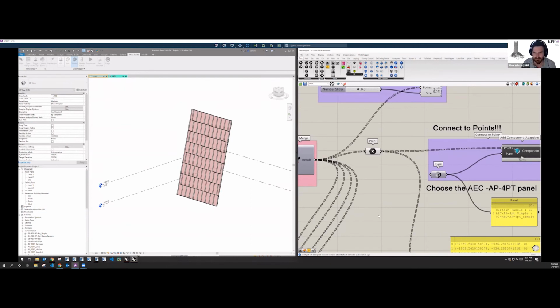So while element binding doesn't exist, what Aniket was bringing up, and I just wanted to say it explicitly because as someone who's run this, switched a panel and then realized all my initial panels got deleted: if you create the panels within Revit and then reset something at the start of the script, literally anything, it will recreate the panels. At that point, it will delete the initial set of panels and create the second. The way around that is either 1, unpinning the panels, 2, closing Revit, reopening Revit, breaking that bind between Grasshopper itself and the panels, or 3, freezing your Grasshopper and doing the old copy paste.